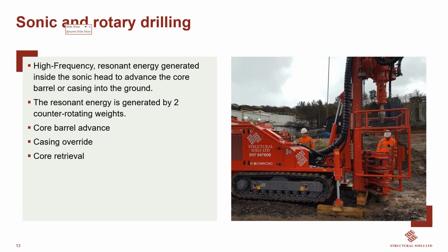Very briefly, Structural Soils were one of the first ground investigation contractors to bring rotary and sonic drilling on the same rig. So we've got a sonic head here and a separate rotary head, which you can't actually see very clearly in this photo. But the sonic drilling is certainly getting more and more used within our operations. We've used it very successfully. It's best for dense gravels and dense sand. It's like a knife through butter.